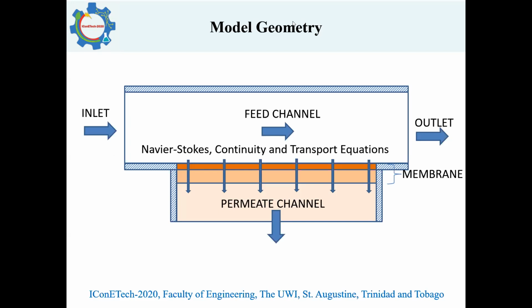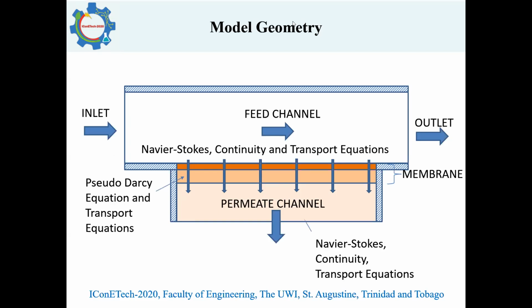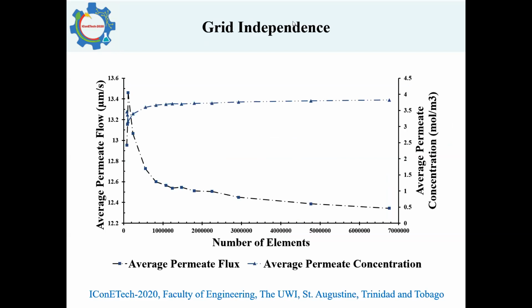Right? We specified Navier-Stokes, continuity, and transport equations in our inlet, pseudo-Darcy and transport equations in our membrane, and Navier-Stokes, continuity, and transport equations in our permeate channel. Right. So before we can actually go about looking at our simulations, we had to establish grid independence.